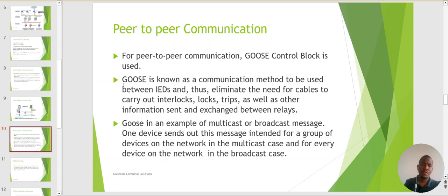In the previous protocol, if we had two devices in one substation and we wanted these IEDs to communicate, we had to run the cable from one bay to the next bay. After the introduction of IEC 61850, since all our IEDs are connected to a network, we just connect a fiber cable or Ethernet cable to the switch, and so on.